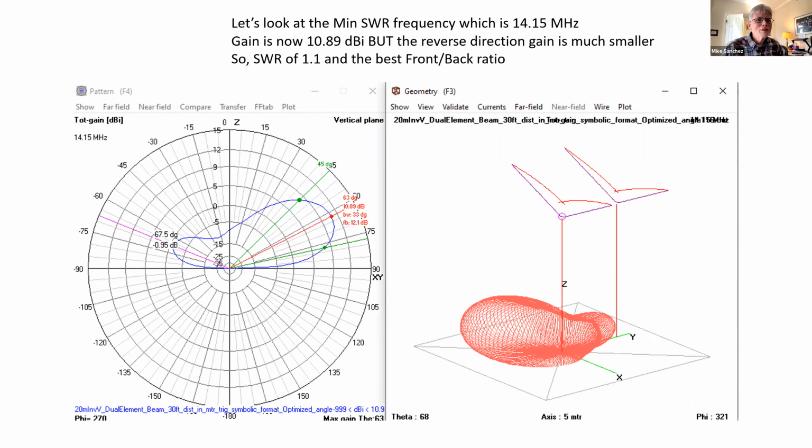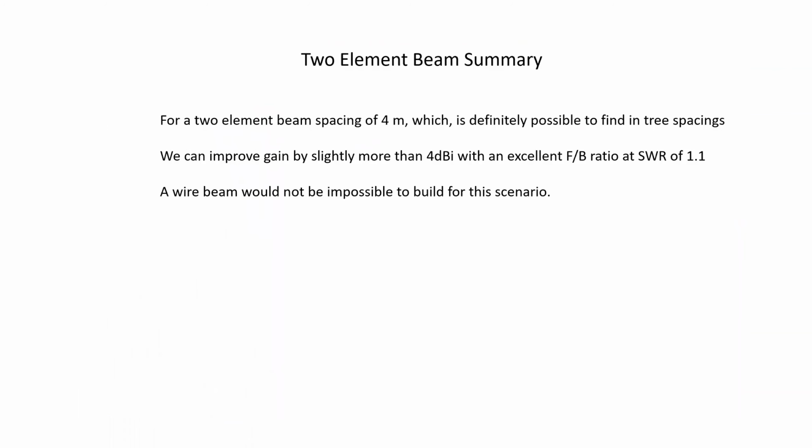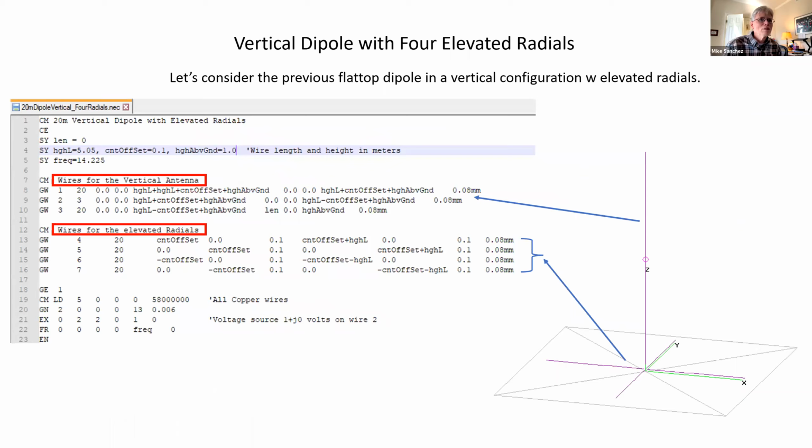Some of the guys in my club are in love with 10 gigahertz right now. I have never used it because it's pretty expensive to get it all put together. But these guys are going all over during these contests and using 10 gigahertz way up in the air, 30 feet, which is pretty far from the ground for a 10 gigahertz signal. You're right. I think there are rules of thumb about how many wavelengths over the ground before you can ignore ground effect. I do not know what they are, but okay, so that's it.